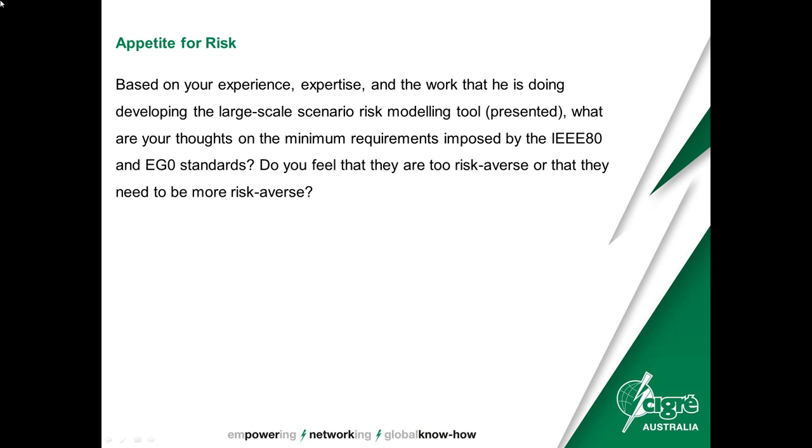So in this question, there's IEEE 80 and there's EG0. They're quite different in terms of their minimum requirements. IEEE 80 was a fairly simple allowable touch voltage. EG0 is saying that really, if you want to be rigorous, it's a risk-based approach to manage risk evenly across things. And that to me is the big difference, and that's why we're heading in the right direction, because we're actually empowering engineers to say this is good use of the funds available and this isn't as good a use of the funds available.